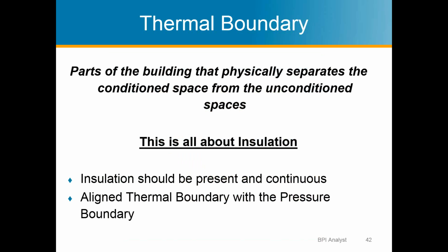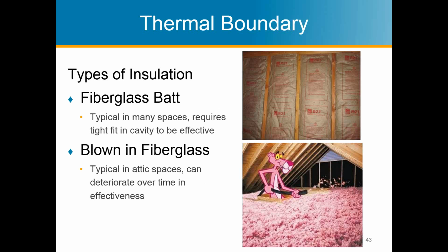So the thermal boundary, it's the physical separation from the conditioned to unconditioned space. It's all about insulation. Insulation should be present and continuous, and it should be aligned with the pressure boundary, which we spoke of.